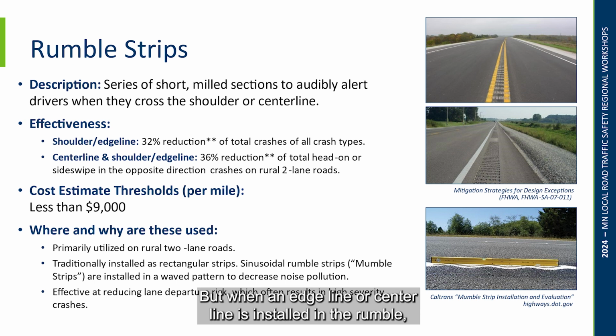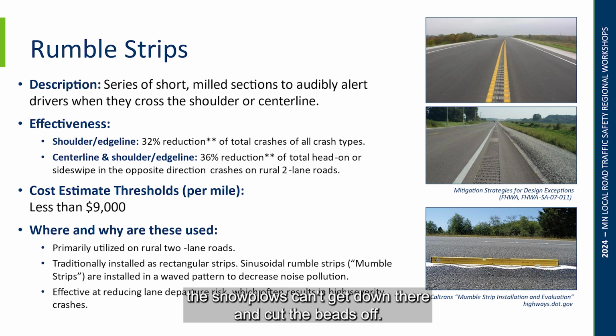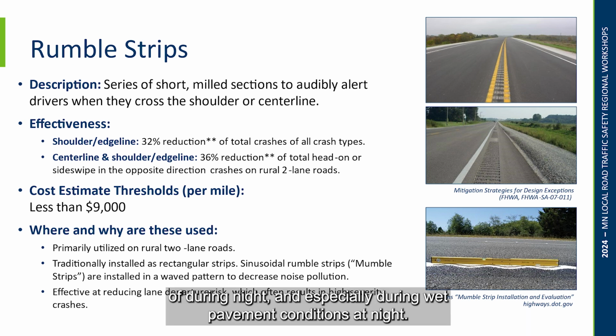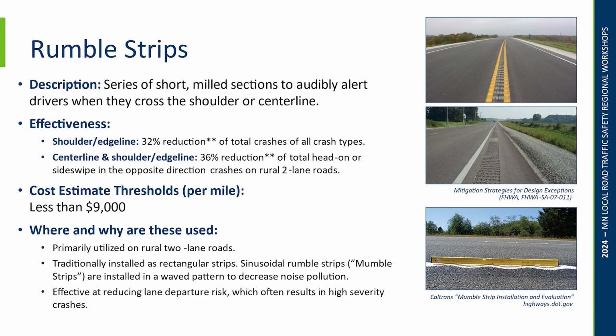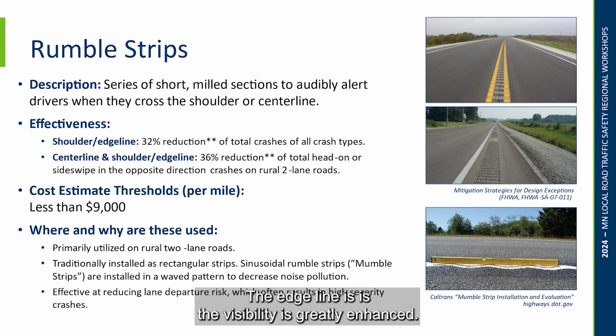But when an edge line or center line is installed in the rumble, the snowplows can't get down there and cut the beads off. And so the sinusoidal rumble has this added benefit of during night, and especially during wet pavement conditions at night, the edge line visibility is greatly enhanced.